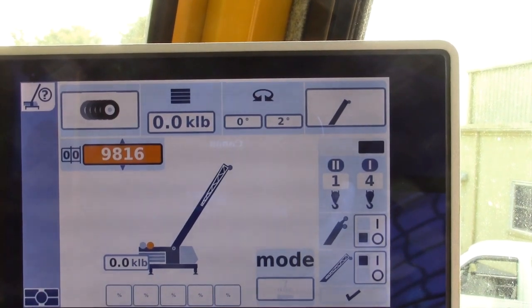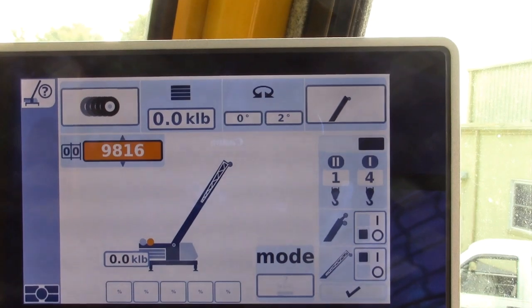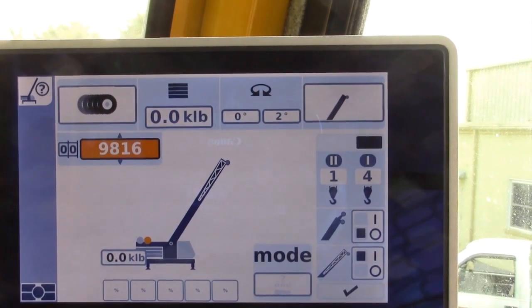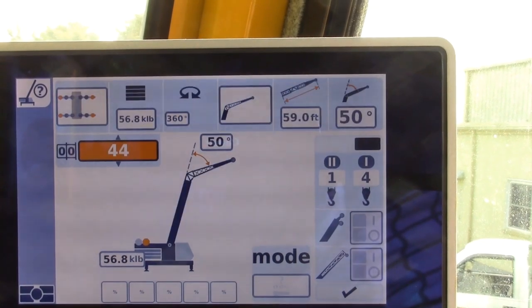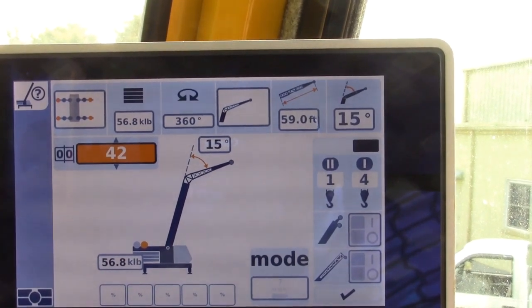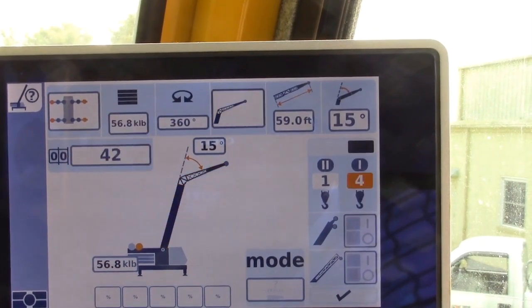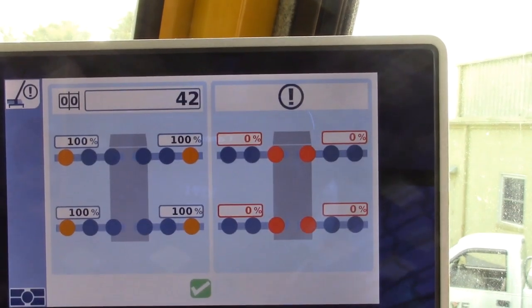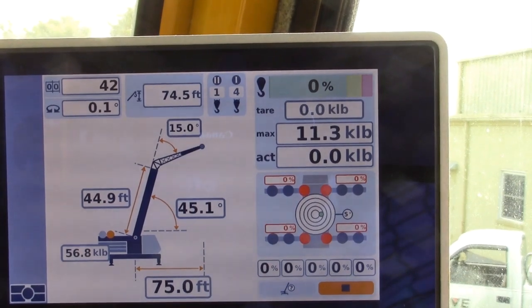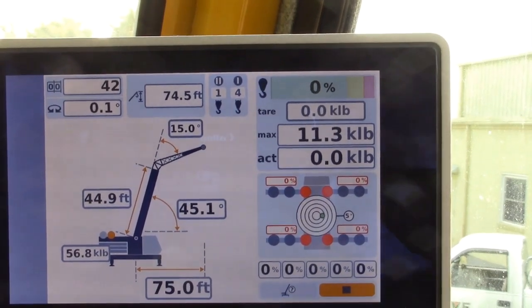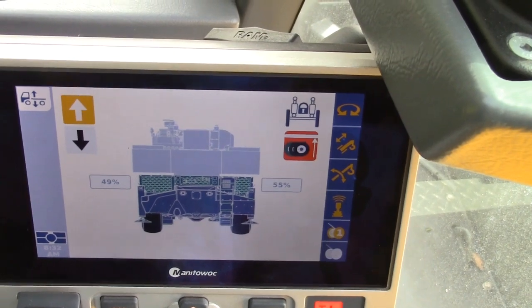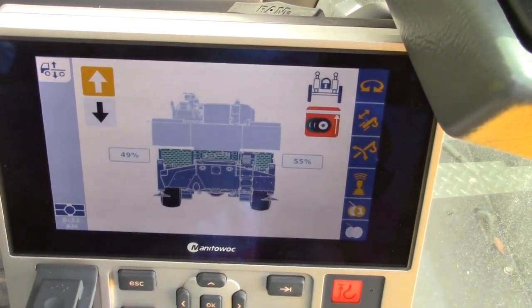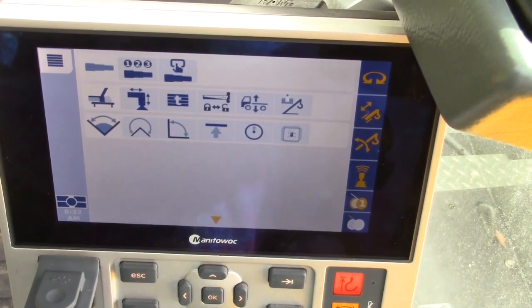Failure to have the crane in one of these 4 rigging codes will create issues on the suspension screen and not allow you to operate. For training purposes, we will intentionally pick a rigging code that is not available to operate the suspension screen. You can now see on the operating display, and we'll back up for training purposes to the home screen.